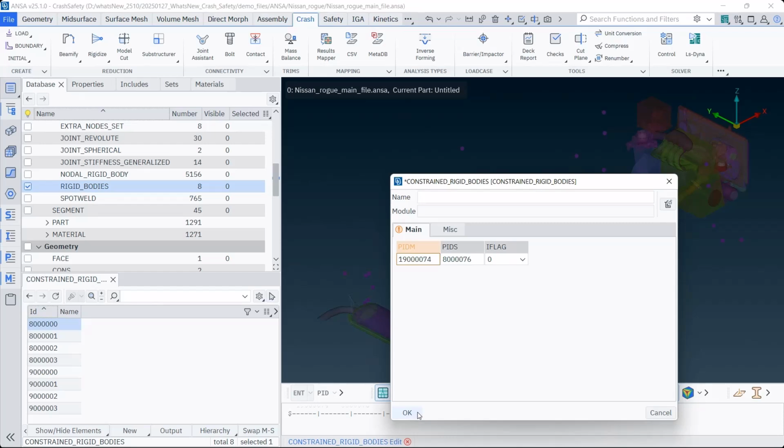The rationale behind this change in the behavior of these specific entities is that materials may reside in different includes. It is possible that one include contains the rigid properties, such as those for constrained rigid bodies, while another include contains the materials. As a result, an undefined material may be assigned, potentially a non-rigid one, if the materials include is not loaded. This adjustment is made to accommodate such cases, allowing for greater flexibility in selecting properties.